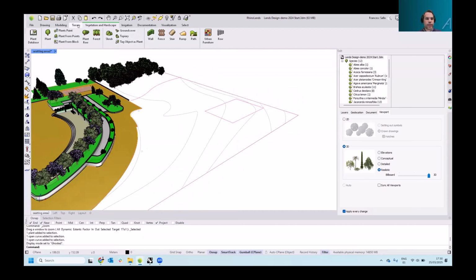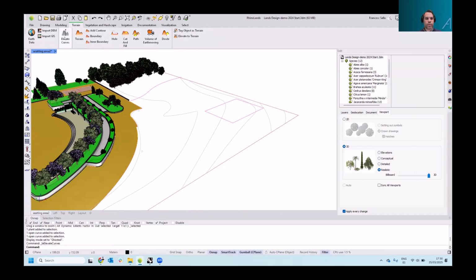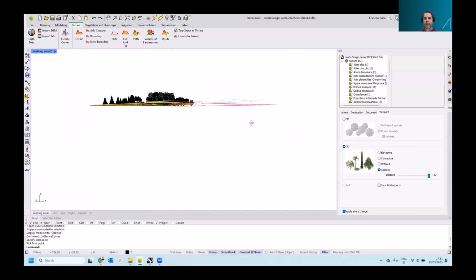And under the terrain modeling tools, we can use this command that will be used to elevate curves according to an interval. I'm going to set this to 1 meter, and then I will click this button to draw a line, and all the curves that intersect with this line will be elevated according to this value, and taking into account this start dimension, which is 0. When I click apply, you can see now that the curves have been elevated.